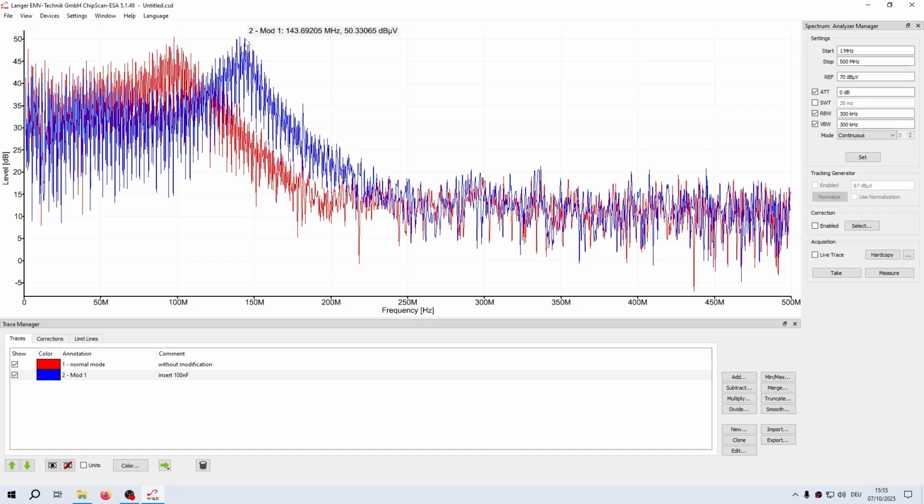and compare these measurements. You can go to the detail and say, okay, what's the frequency range of this? For example, here this resonance is located at 140 megahertz. This resonance here is at about 100 megahertz. And with these marker points here, you can go through these measurements and see what the specific frequencies are, or if you see some harmonics or some other frequencies of your device.